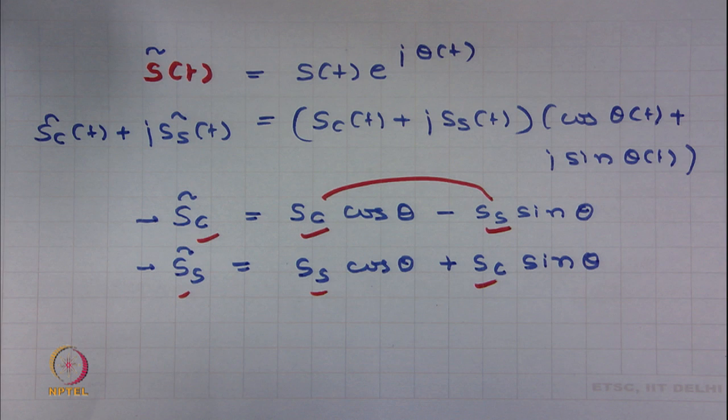That is one way. The second way, and the way it is done, is that instead of shifting the frequency and phase of the carrier, which is difficult to do, you take care of this effect in the baseband domain. So, you do not touch the carrier that you are using at the receiver, but rather you take care of this effect at the signal processing level, at the baseband level, at the computer level.